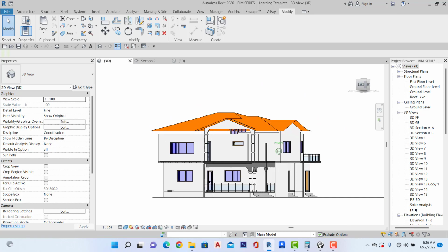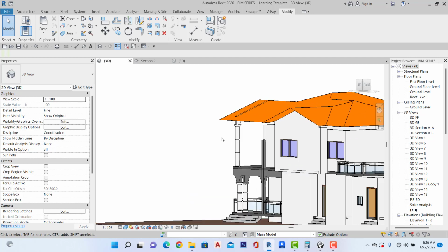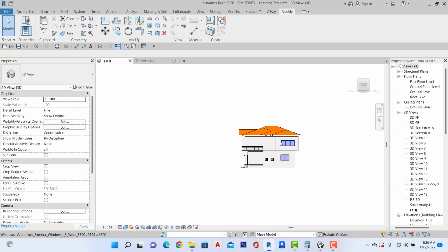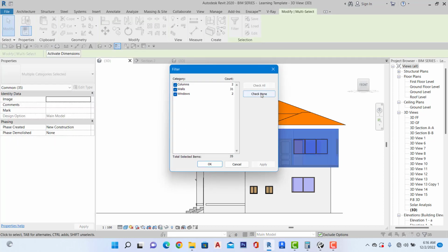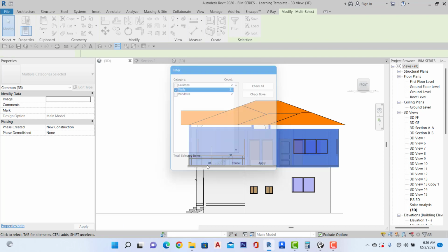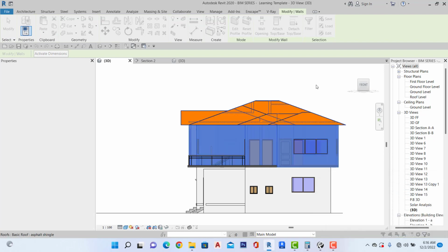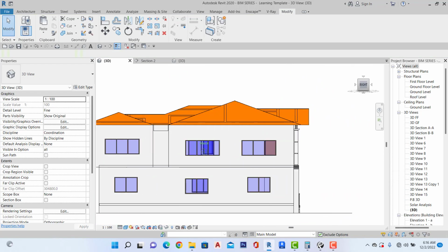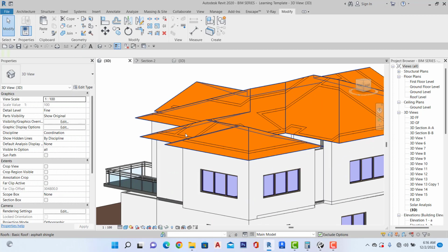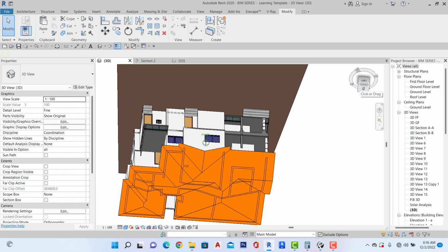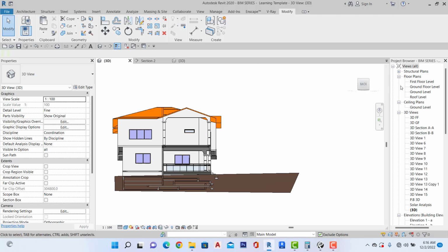So what we are going to do next is to how to create what? A ceiling. But first of all, I'm going to select all these walls here, filter them, and also choose poly wall. Then I'll do attach to roof. So after attaching to roof, now the walls have been attached to roof, so we have something like this.